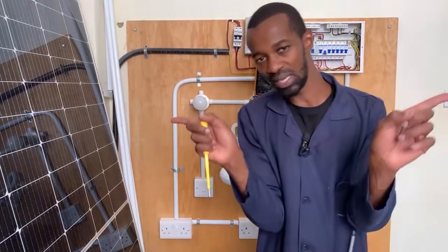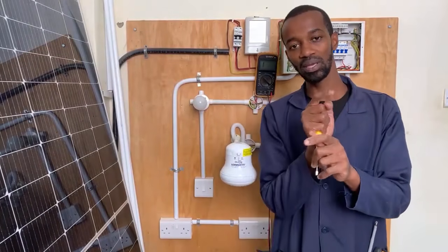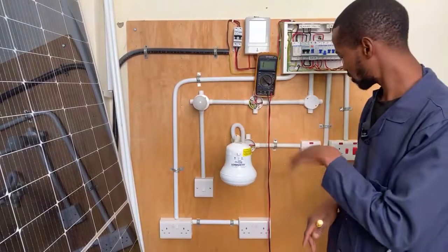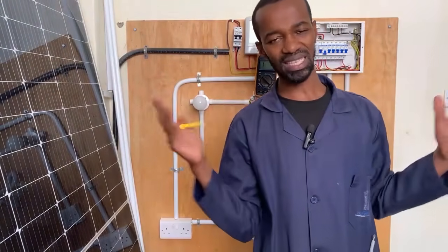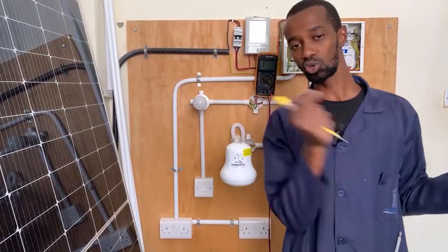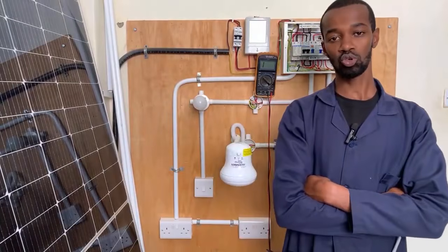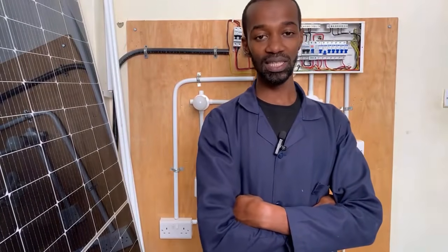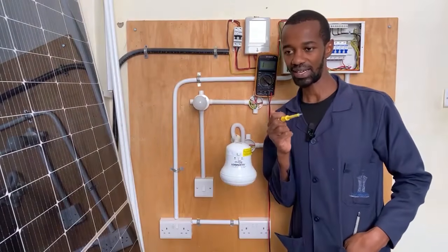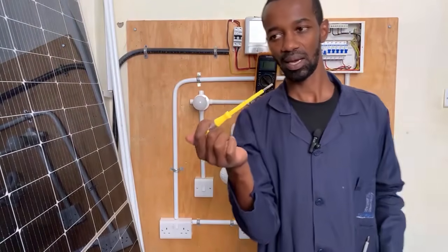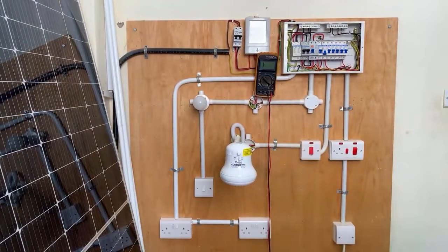If there is an opening in the circuit and you probably have the MCB not tripping, but again, circuits are not powering, for instance this switch here, you will definitely know that there is an open circuit. This normally happens when there is a loose connection, especially on the phase or the line. A loose connection on the neutral manifests itself in this manner. There is a return voltage or current that, when you place that tester on the neutral, you will be able to experience it.